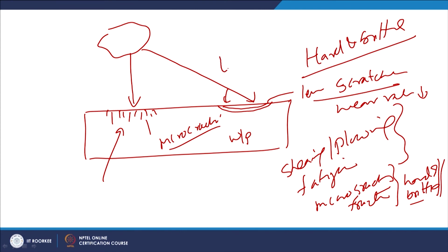So, there is low erosive wear for low angle impingement as compared to high angle impingement in the case of hard and brittle material. So, the angle of impingement and the workpiece material properties are the two crucial parameters which govern the loss of material from the functional surfaces by erosion.